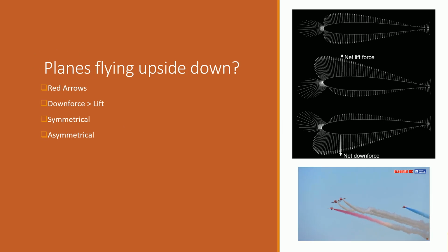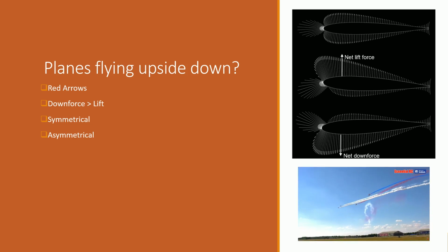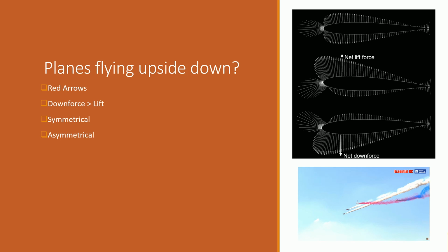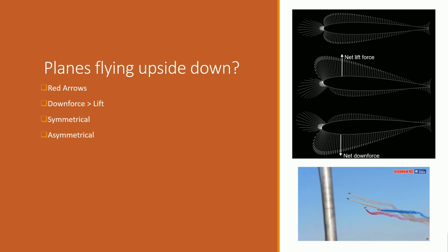Looking at the red arrows on your right, you might wonder how an aerofoil could possibly fly upside down. Planes just don't do that, right? The truth is that all that is required for an aircraft to fly upside down is an aerofoil that can produce more downforce than lift, usually at small negative angles of attack. See the pictures of the symmetrical airfoil NACA 0012.